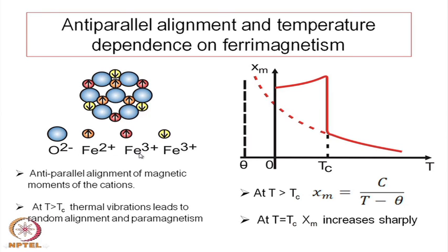These two are in the octahedral structure and this is outside, so this is tetrahedral. So, half of the Fe3+ goes to the octahedral and half goes to the tetrahedral, and it is represented like that. The yellow ones are the octahedral sites, this is the tetrahedral site, whereas the reddish ones are the octahedral sites.